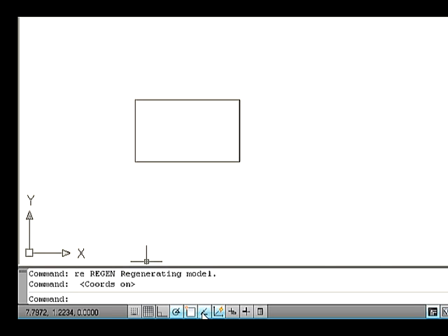Object Track button. Object Track is also an AutoCAD tool for ensuring precision drawing and editing. You can use the Object Track button to track and grab points on existing objects. Allow and disallow dynamic UCS. You can use the dynamic UCS to create objects on a planar face of a 3D solid without manually changing the UCS orientation. During a command, the dynamic UCS temporarily aligns the XY plane of the UCS with a planar face of a 3D solid when you move the cursor over the face. When the dynamic UCS is active, specified points and drawing tools, such as polar tracking and the grid, are all relative to the temporary UCS established by the dynamic UCS.